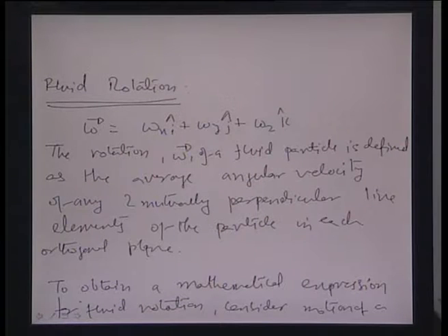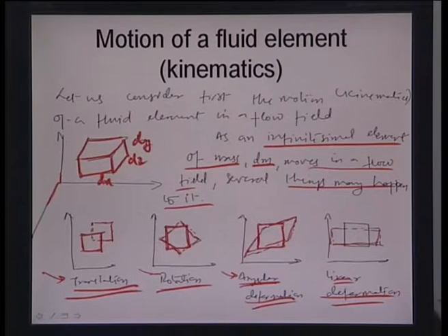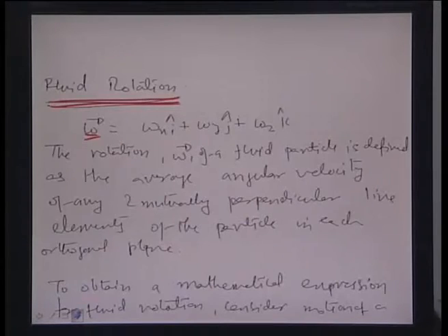Okay, so let us consider the first aspect, that is fluid rotation. How would this small fluid element be rotated? So let us assume that omega is the angular velocity of rotation. If you recall, rotation is the case where you have a block at one angle and one position, and it rotates about its own place, retaining the center, and goes to a different orientation. So let us assume the angular velocity by which it is rotating is omega. So omega will again have three components, omega x i, j and k, which means that these omegas have different axes in which they have independent rotations.